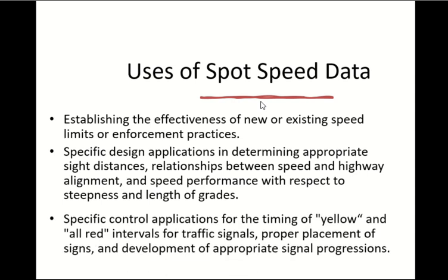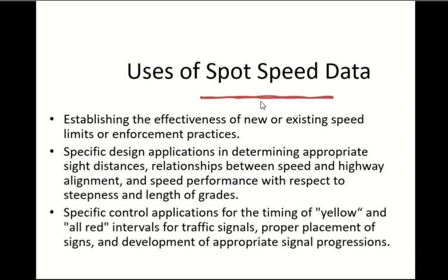Second and third points are related to design. When you are designing, for which case do you design? Worst case or the best case? Worst case. In terms of the speed, which one is the worst case? High speed or low speed? High speed. Why is it the worst? Is it not good for the driver going at high speed? Biggest accident. Because of the safety. Okay, you design for safety, right? Your main objective is to ensure the safety. So in terms of safety, high speed is the worst.